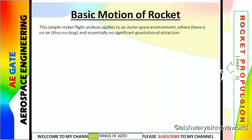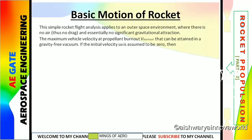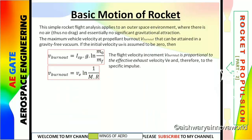Next I will come to the basic motion of a rocket. Here I have already said that this equation has no aerodynamic forces or gravitational forces, that means no drag. Now when you are maneuvering in a gravity-free vacuum condition, when your initial velocity is 0, we get an equation like this: V burnout equals Isp times g times the logarithm of m naught by mf.